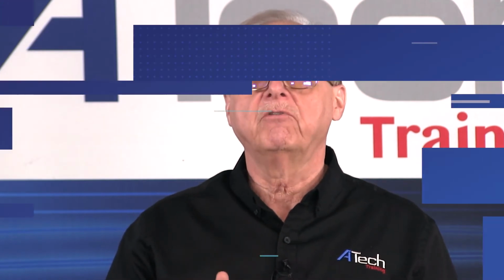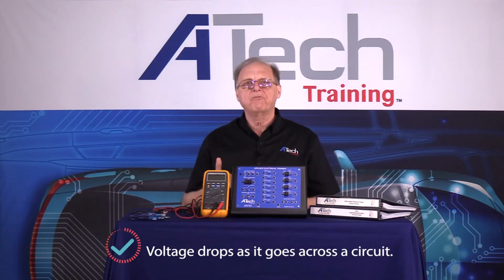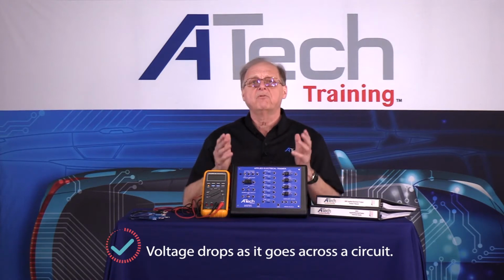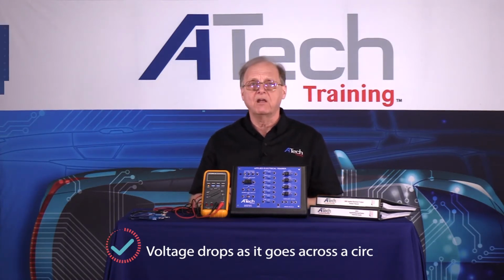You're going to learn the most critical test that you're going to learn on this one. It's what's called voltage drops. If a person understands voltage drops, they have ability to diagnose the circuit properly. Because if you keep in mind, voltage always drops as it goes across the circuit as it's being used. So it's something you have to learn and transmit to your students so they learn it so they can apply it when they get out in the field.